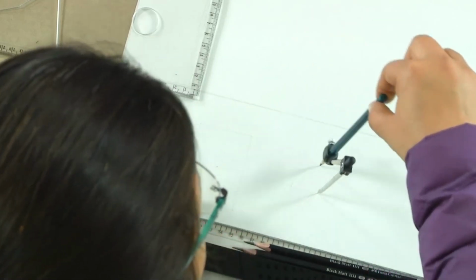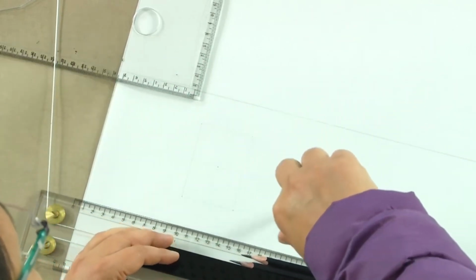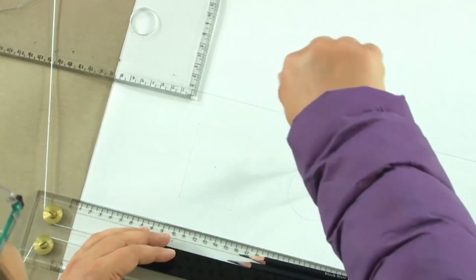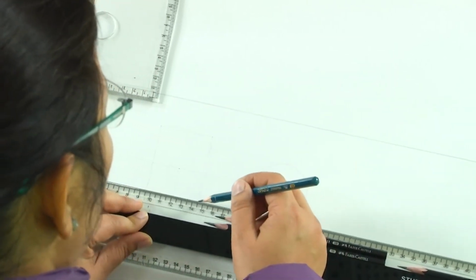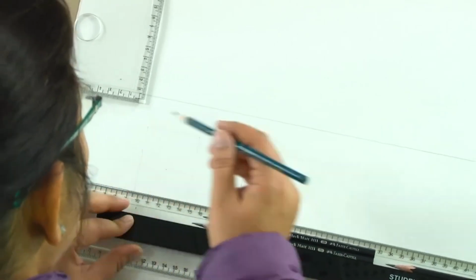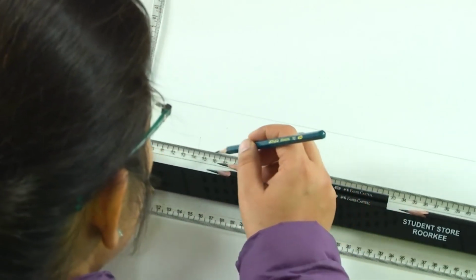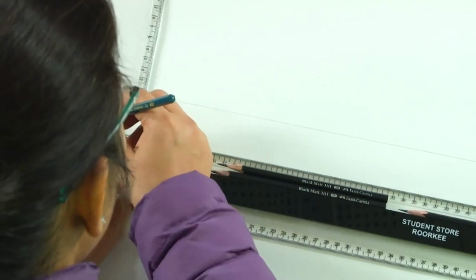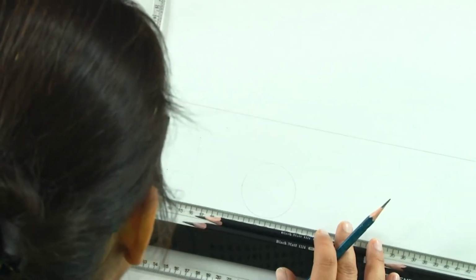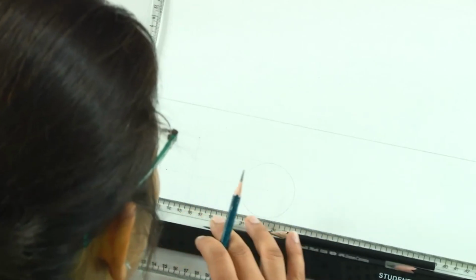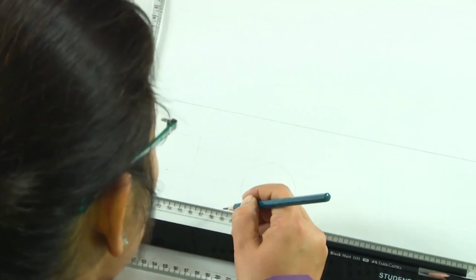Just making a reference image here, which is the base of the cylinder which is intersecting. When we see it from the top, what do we see? We will see that this cylinder is passing through it. Given the total length of the cylinder, let us assume that the total length of the cylinder is say 12 centimeters.